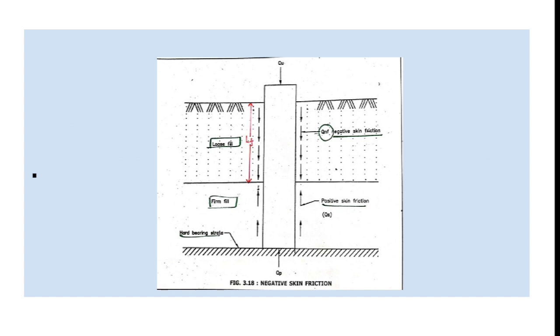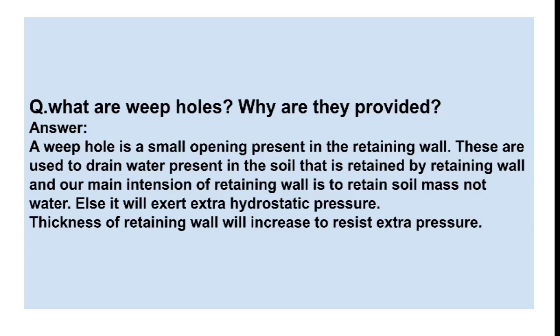Now you can see in this photo, the pile is present in the soil and the soil is settling more than the pile. So some pressure is exerted by the soil on the pile. Due to this, the load carrying capacity of the pile is decreased.